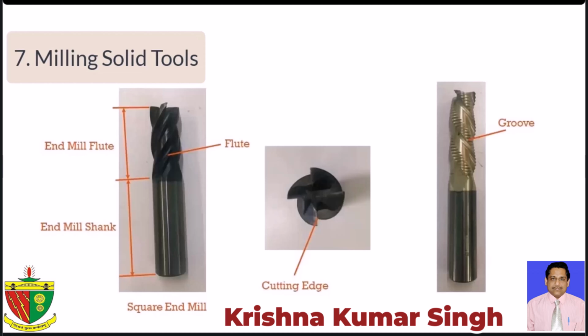On the right, you can see an end mill with a gold-colored coating. The grooves on this end mill help minimize vibration but leave a rough surface finish. These types of end mills, also called hog end mills, are mainly used for roughing.